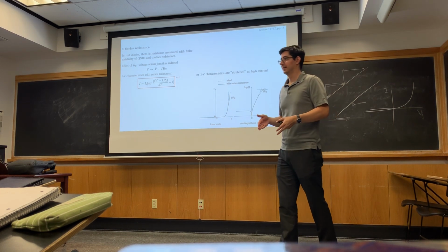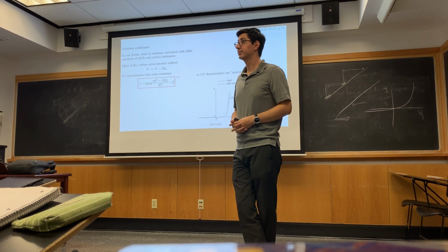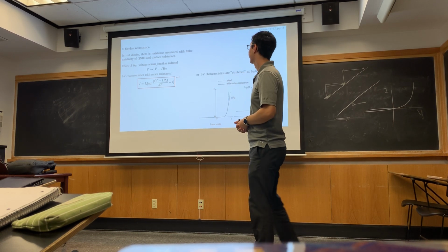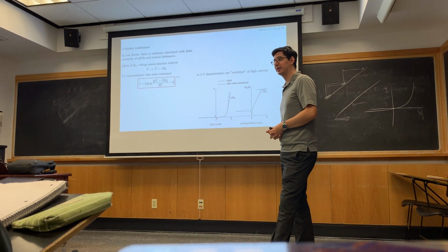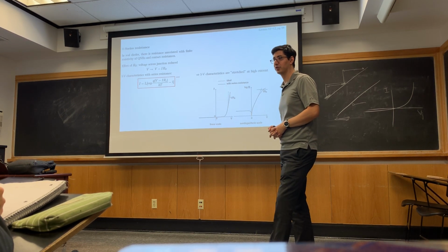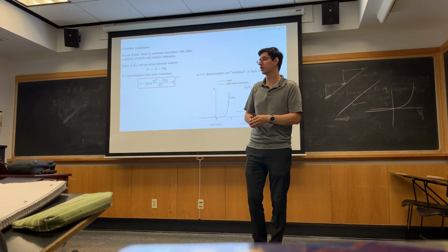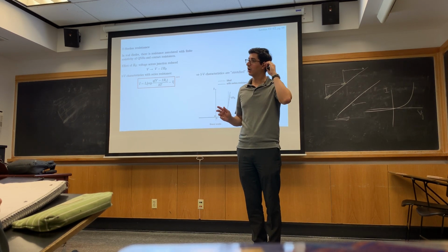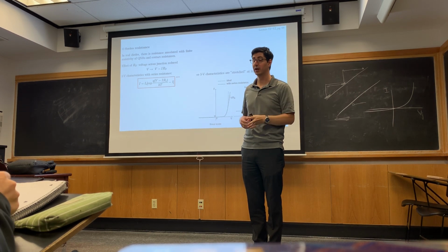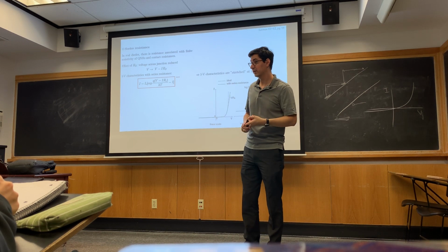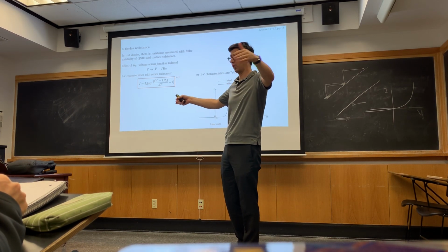It may not be the highest resistive element in this series combination. So we can actually deal with this quite simply if we just lump all the other resistances together and call it RS. RS stands for series resistance. It's just some resistance in series with it. It could be due to the quasi-neutral regions, the contacts, or other elements, like the wires connecting.